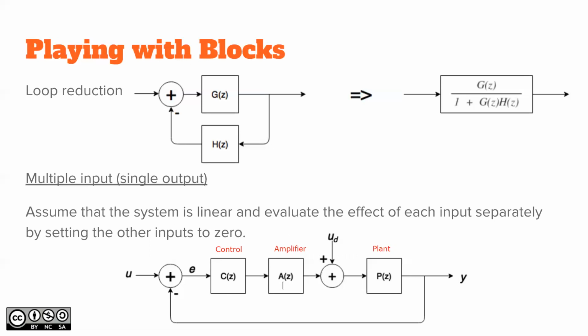And of course, it also has some transfer function. Usually it operates as a low-pass filter, or if the plant requires a PWM signal, then this amplifier part would be the PWM driver. The control signal controls that output, which goes directly to the plant. Okay.